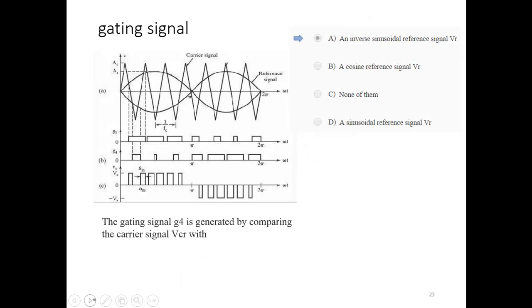Now, what you do for the first pair is drive the first transistor Q1 with the positive sine comparison, and the other one you compare with the negative sine. For the first one you do positive 1 and 2, and the other, 2 and 3, is the opposite, the inverse of that. This is for G1, and the other is the opposite of that. This is what you do for the gating of the first pair, and the other goes in the opposite direction. That's how it is generated.